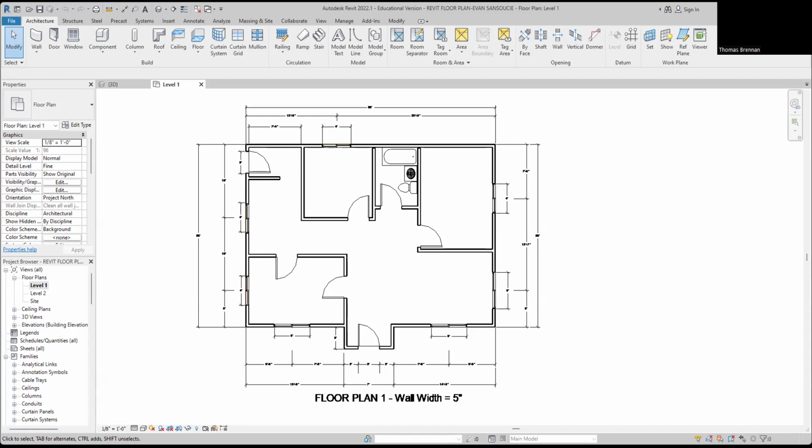So get your 1/4 inch. Let's see here. May have to flip it around. Yeah, okay, that's the one right there. So start over this side. Put your 0 right up to here. Check this out. That goes right to there. See how that goes right there? And then this goes right down like that. When you get those perfectly, see how the lines are perfect at 8 feet? Yep, 0. Okay, and that's 8 feet right there. So that's how that works.